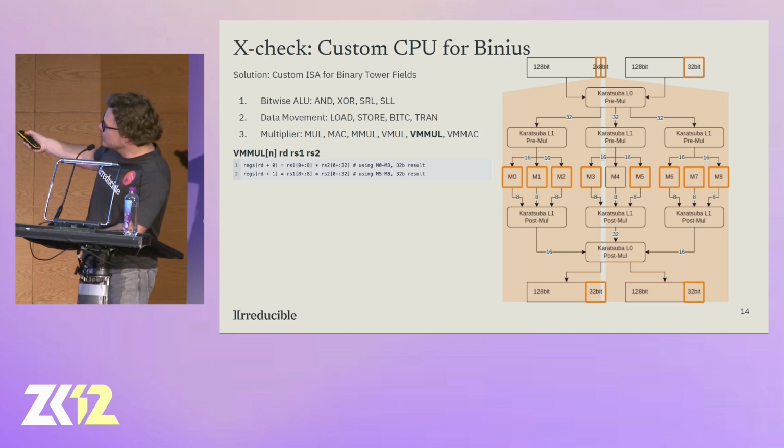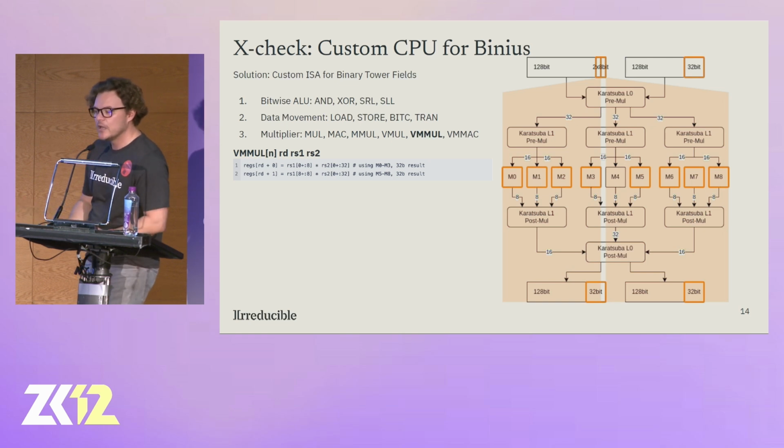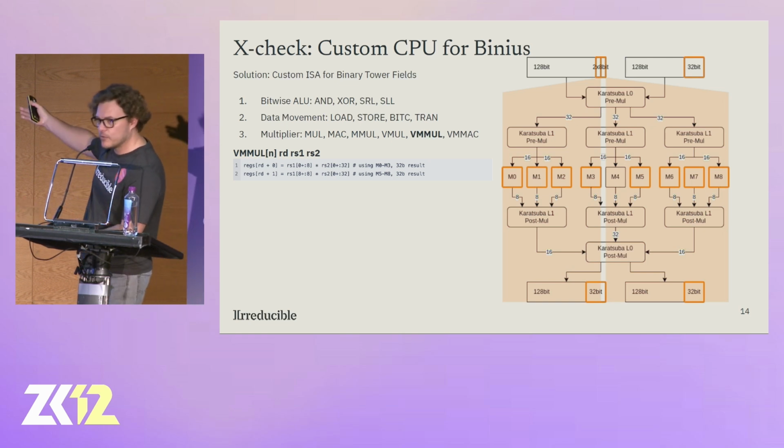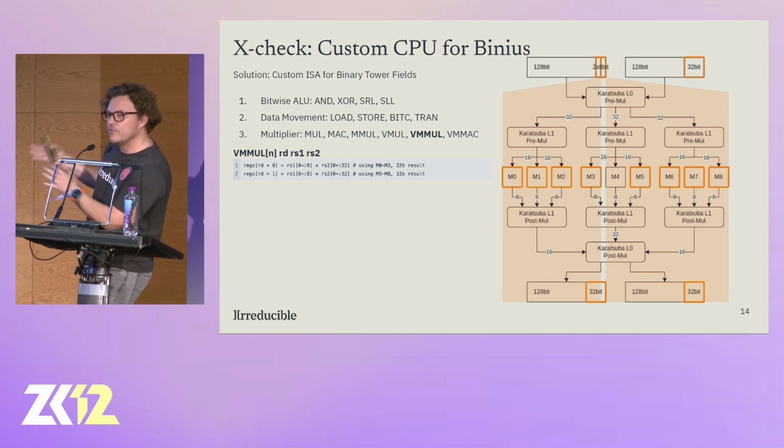Again, in this example, we are taking 2 8-bit operands from the same 32-bit register value, but the left-hand side 8 bits only propagate through this circuit, and the right-hand side 8 bits only propagate through this circuit. This time utilizing 4 multipliers each. M4 is not really used in this case, but this gives us 2 results in parallel on the same clock cycle. This is another example of a very exotic approach to multiplication, which is informed by cryptographic properties and how we can mix and match small or large fields.